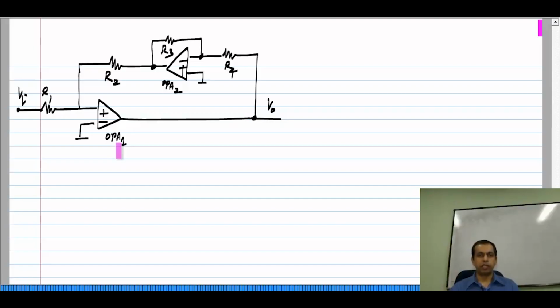I mean, doing that calculation, you have to do something with the rest of the op amps in the circuit. The easiest would be to assume that all other op amps are in negative feedback, so their inputs are virtually shorted. Now, sometimes you cannot make that assumption because that will lead to a contradiction, that is, some Kirchhoff's law or some circuit law will be violated. In those cases, those op amps which are giving you trouble have to be modeled instead as a voltage controlled voltage source, which is the model for the op amp with a finite gain. Okay. And then you proceed with the analysis.